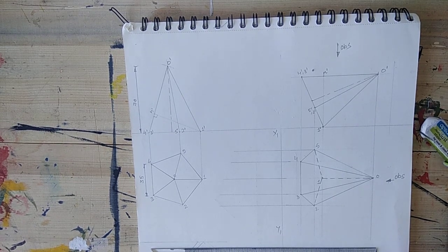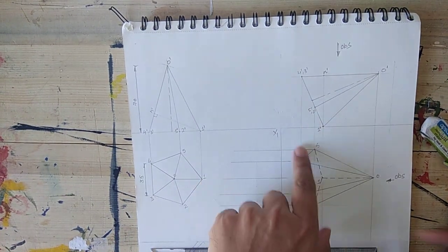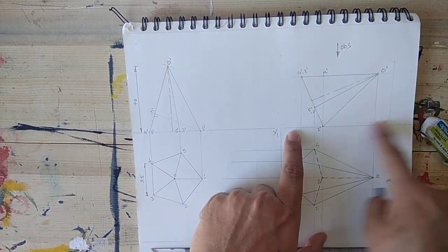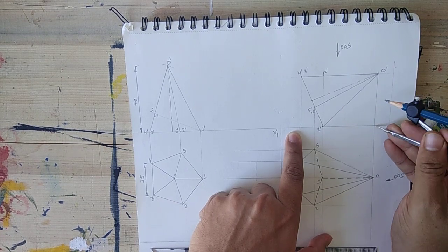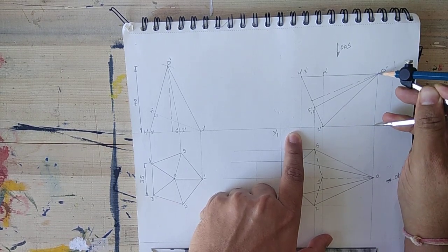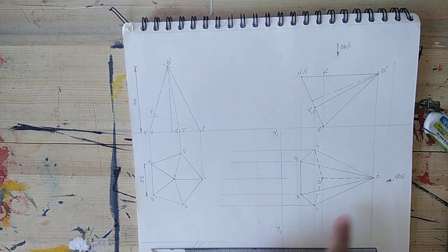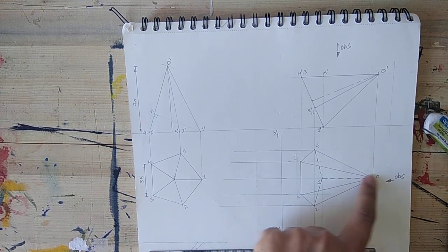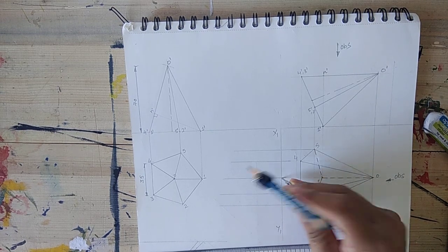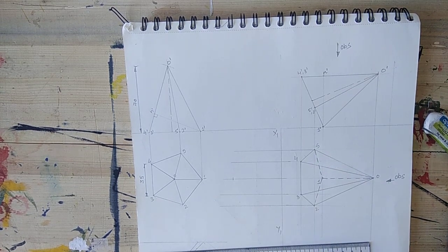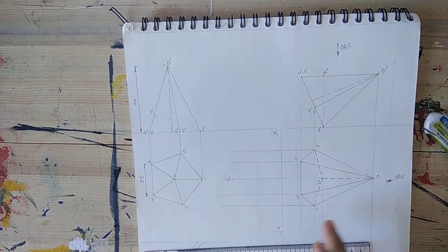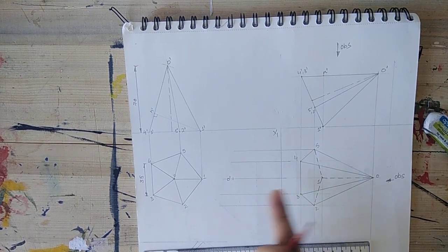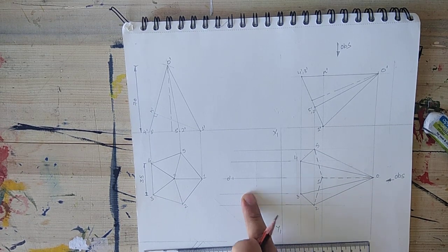Okay, after that class we will mark the vertical distance of all points of the front view from the previous reference line. Start with O, so this is the previous reference line, then this is the vertical distance of O, then mark projection of O. This point is your O dash, because this is HP, so this is your new reference line and this plane is your VP.